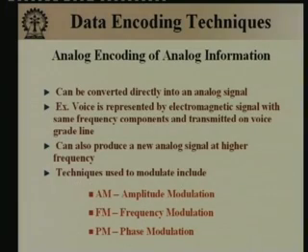So, there is a very high frequency so-called carrier wave, which is carrying this 4 kilohertz signal. If it is only voice, of course; if it is music, you may like to have somewhat higher bandwidth also. But anyway, that is also an analog signal, this is also an analog signal. So, one analog signal is carrying the other analog signal, and there are various ways of doing this, so-called modulation. The three most common ones are amplitude modulation, frequency modulation, and phase modulation.